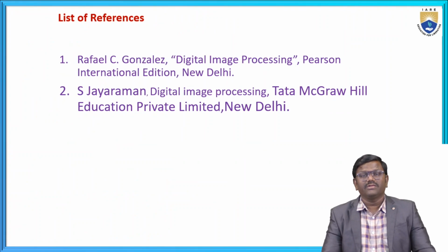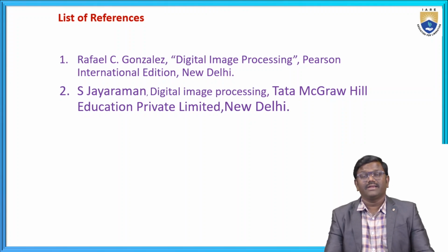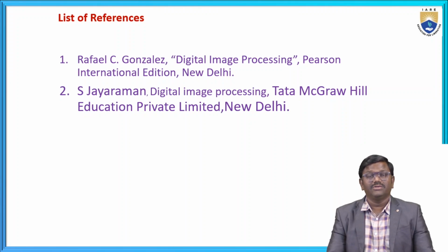So I hope you understood that today's topic is one of the very important topics we call the spatial filtering process: how to classify it, and once classified, how to extend it and apply it as a spatial filter on a gray level image using the neighborhood pixel principle.